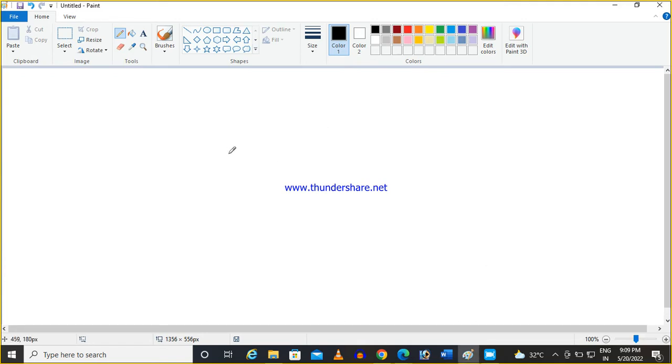So say the equivalent circuit already I have drawn. Say this is the capacitor, and this is the initial charge of the capacitor. Now, as I told, here to restrict the inrush current, we need to add here some resistance.